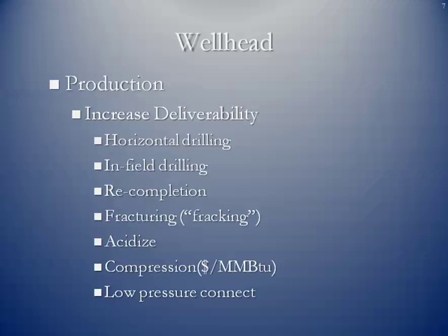Again, because we're interested in the production and the deliverability, these are the sales volumes. So we want to know what are the ways in which we could actually increase the amount of gas flowing from a natural gas well. Well, I think by now we're all familiar with horizontal drilling. Horizontal drilling allows you to pull more out of the reservoir than straight vertical drilling. Another method would be to basically drill another well, or what we call infield drilling. Go ahead and drill an offset well.